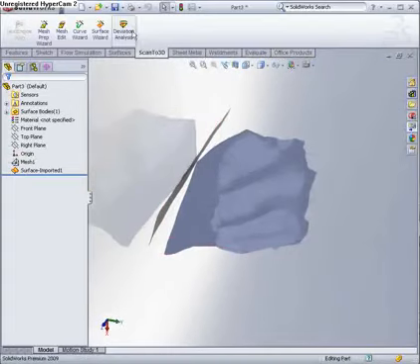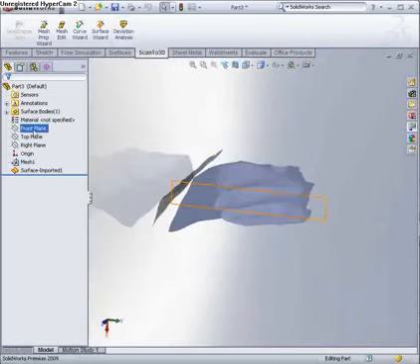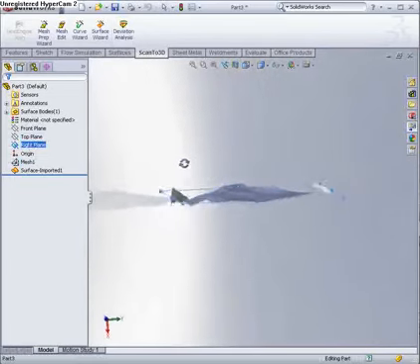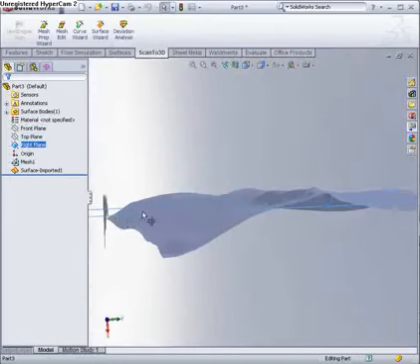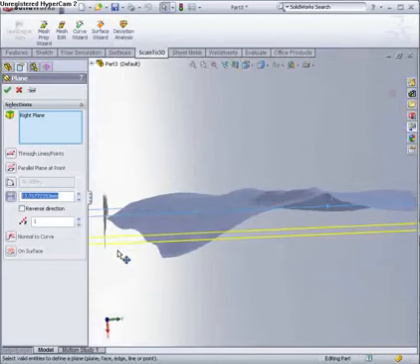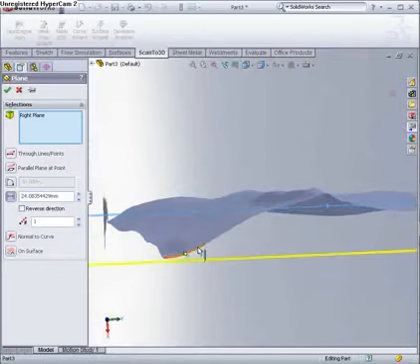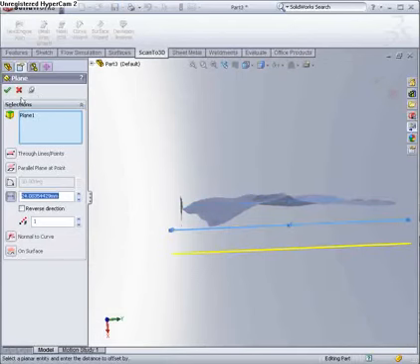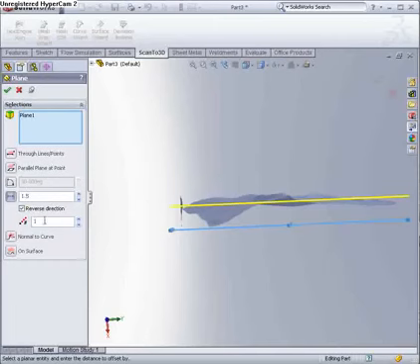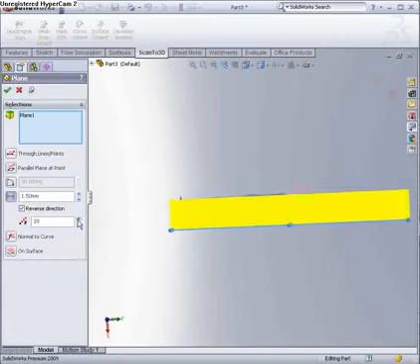So what I want to show you is creating a topographical map from this model. So what I'm going to do, I'm going to copy down this plane to just below the model. I'm going to pin that command, we'll leave it there, and I'm going to make these. Don't want too many of them just because it takes a little bit longer to process. So 22 planes, so each of those intervals, so you can specify where you want them.